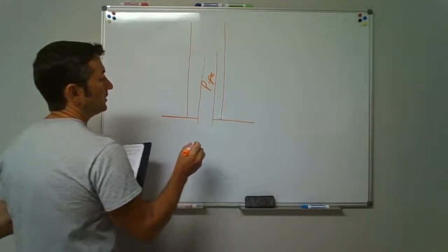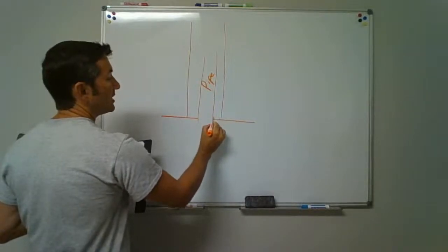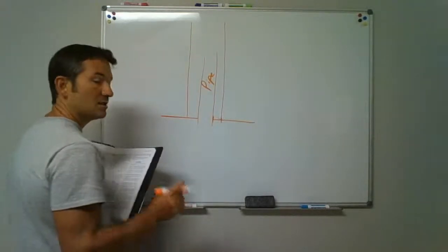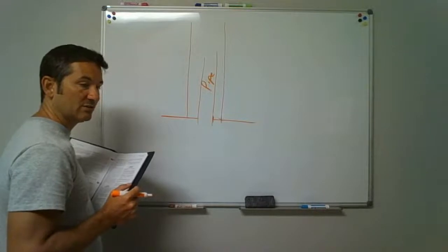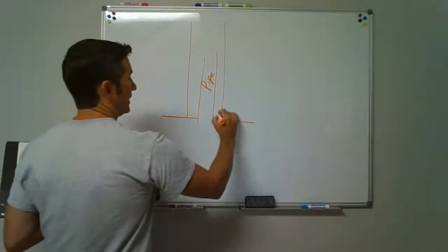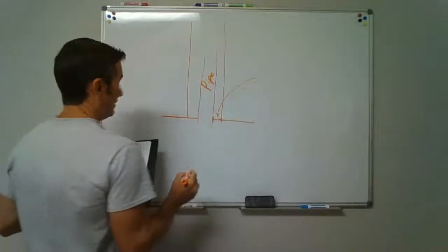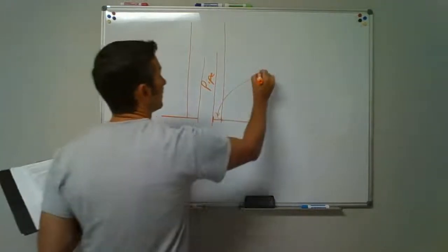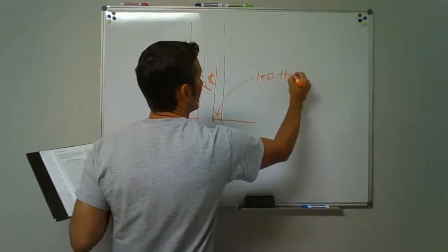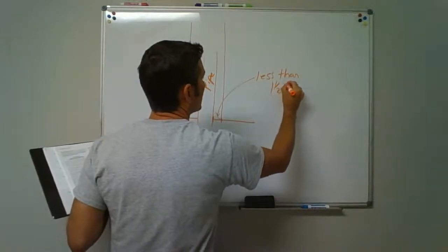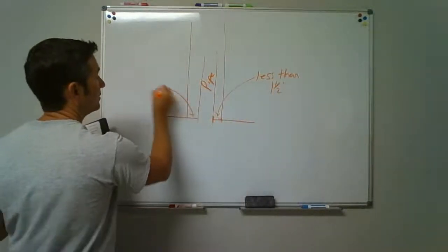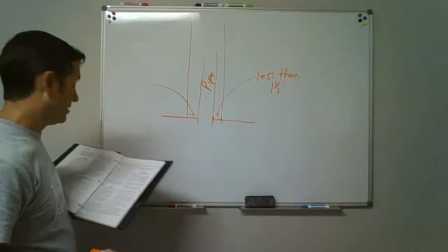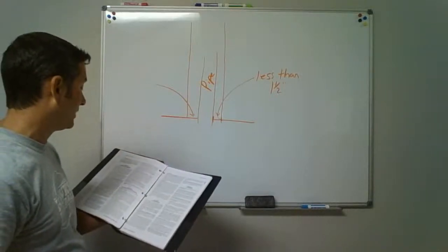What it's referring to is how much room do we need from the edge of the pipe to the edge of the framing member, to not have to put a protective shield plate. So if this area is less than 1.5 inches, and that goes for this side as well, if that's less than 1.5 inches, you have to put a protective shield plate.